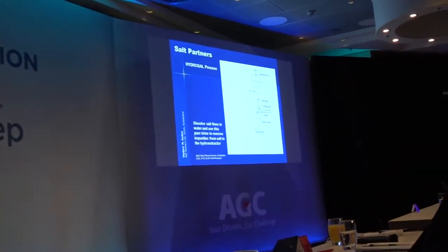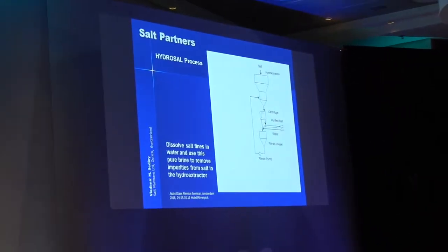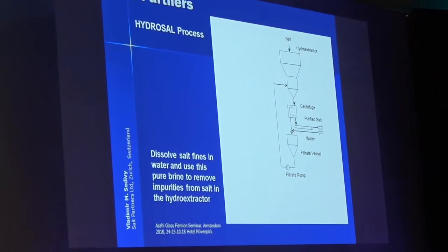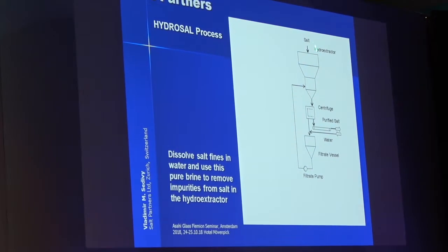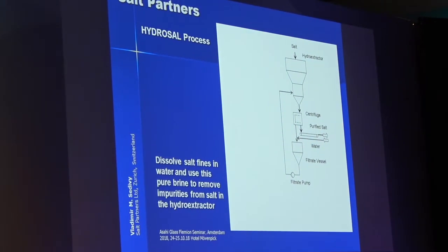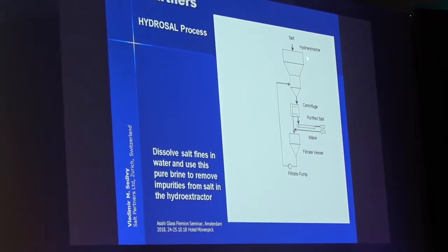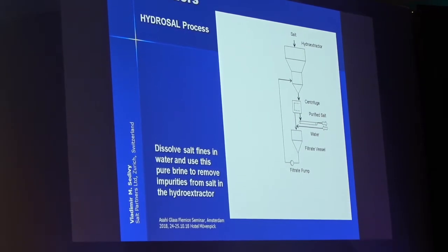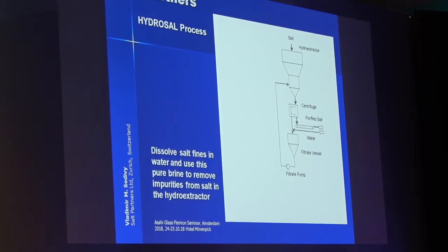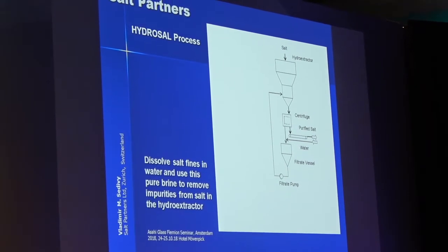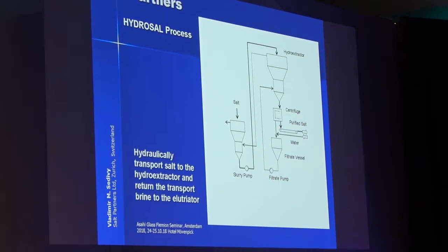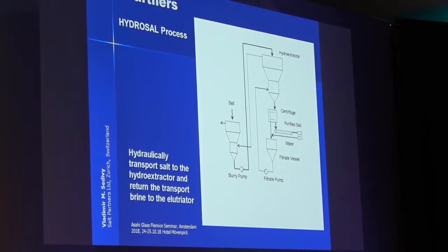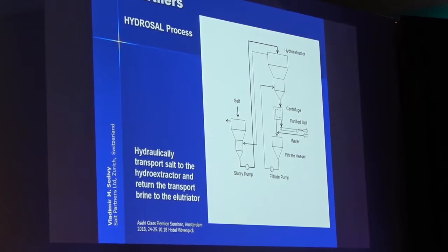And we have added water into the filtrate vessel, dissolved the fines, and used this pure brine in a vessel or in a decanter above the centrifuge for countercurrent purification.